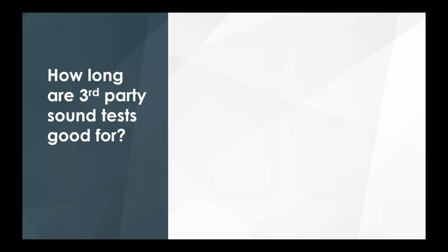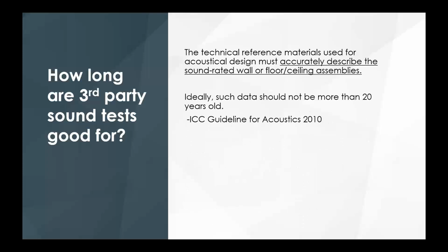All right, back to the knowledge on this. How long are third-party sound reports good for? According to the guideline for acoustics from ICC, it's no more than 20 years. That's what they're looking for. That technical reference is going to specify the material and how it's built. It's going to give you a full description of that wall assembly, and it shouldn't be more than 20 years old. So always ask for a copy.